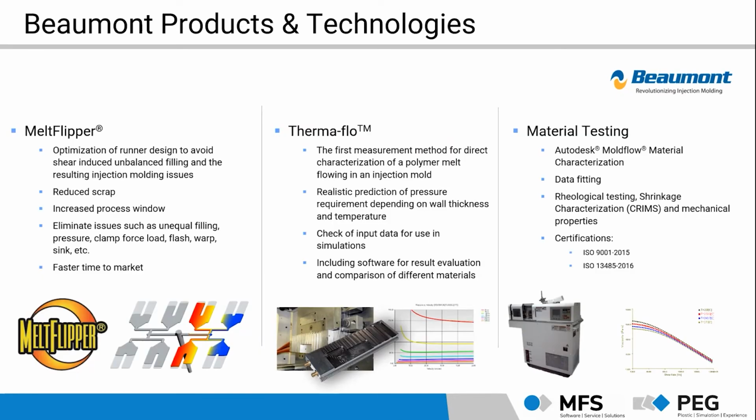First of all, a short overview about the collaboration between Mf Software and Beaumont. We started our partnership in around autumn 2018. Since then, Mf Software is the exclusive European sales representative for the three products or services that you can see here. On the one hand, the MeltFlipper technology, which is an optimization of the runner design to avoid unbalanced filling in most cases in multi-cavity tools. This is the topic that we want to deal with today.